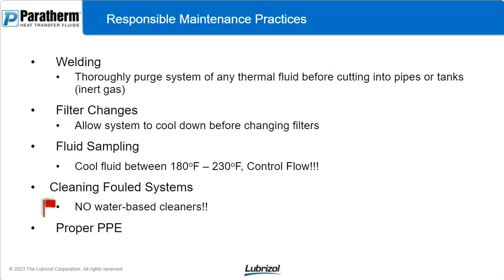And then just follow maintenance practices that are responsible. Make sure you're cooling things down before you're working with them, and purge any fluid or vapors out of your pipes for welding. If you're sampling a fluid for a fluid analysis, make sure it's cooled down. If anybody comes in and tries to sell you on a water-based cleaner, even if the fluid's out and they promise you they'll get it all out, big red flag, don't do it. Too many times we've had people just completely waste new charges of heat transfer fluid because of all the water left in the system. And always wear proper PPE.